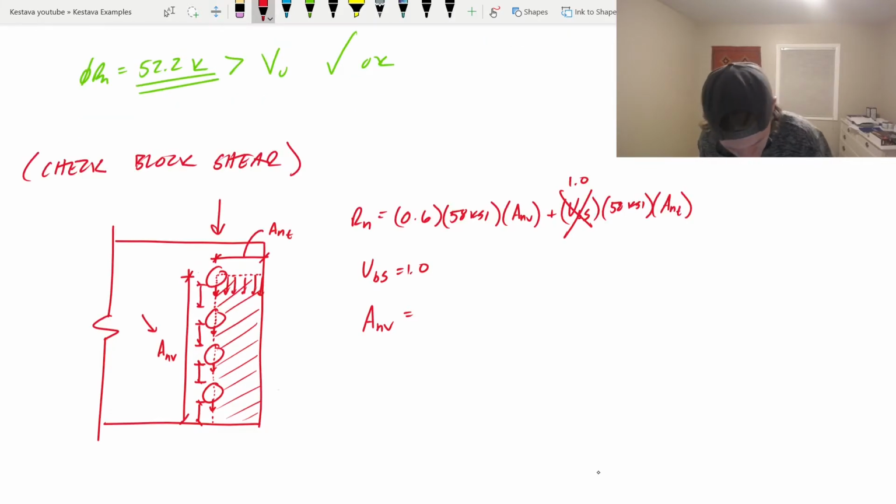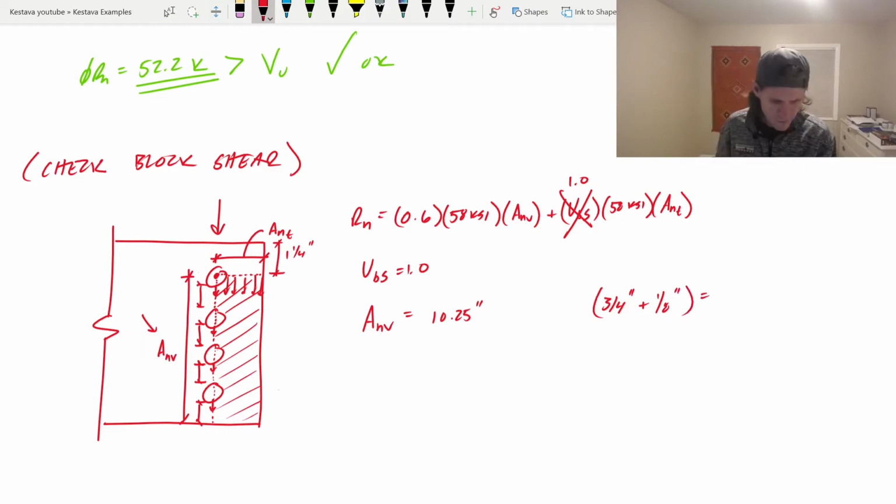So what would I do? Well, first I know that the top here to the center line of the bolt is 1 1/4 inch, and we know that just from the problem up at the top. That's to the center line of the bolt, right in the center. So from that point further down, that would be 11.5 inches minus 1 1/4 inches, which equals 10.25 inches. We need to subtract, well, what would I do here? I would first say, what do we say above? 3/4 inch diameter plus 1/8 inch for the full hole diameter of 0.875 inches.